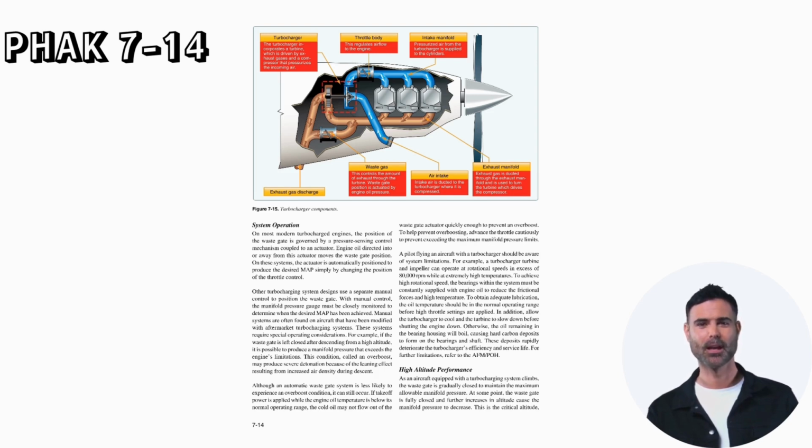In addition, allow the turbocharger to cool and the turbine to slow down before shutting the engine down. Otherwise, the oil remaining in the bearing housing will boil, causing hard carbon deposits to form on the bearings and shaft. These deposits rapidly deteriorate the turbocharger's efficiency and service life. For further limitations, refer to the AFM or POH, High Altitude Performance.